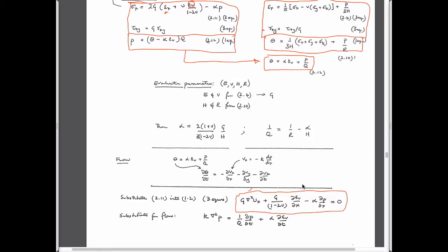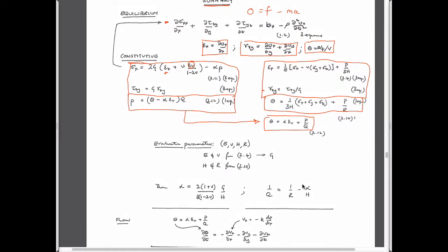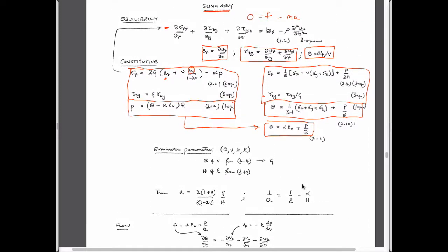The complicating factor a little bit for the way that the Biot derivation goes through is that it defines behavior in terms of these not so obvious coefficients, H and R. Shear modulus and Poisson ratio we certainly know, but also in terms of the values of these other coefficients.